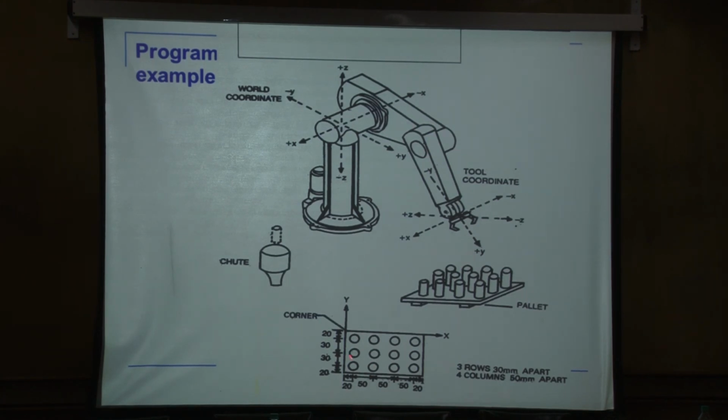So the way robot programs are written these days is essentially to have each task as a function or a subprogram. For example, spot welding, spray painting, pick and place. So whenever the programmer needs to do some task, he will simply refer to that subprogram, call it, do the function, and then come back to the main program again.